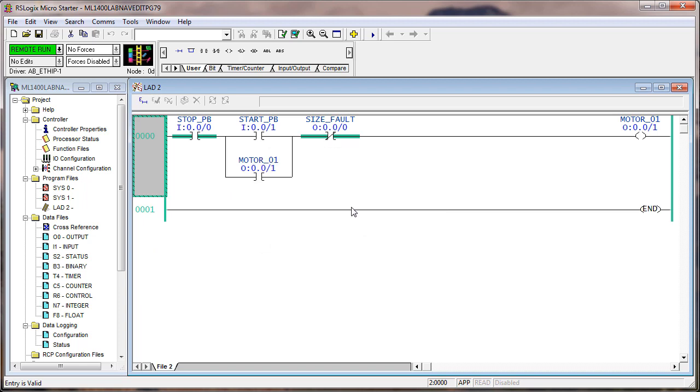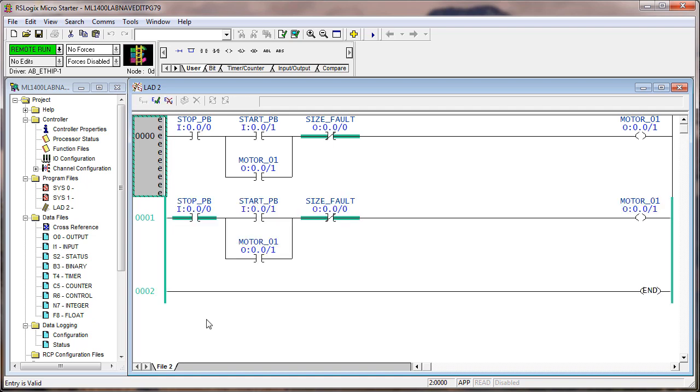And I'm going to add a second rung, and because they look similar, this one's the focus, so Control C, Control V, and I've got another one that looks just like it. And I'll move this one down here. That way the one I'm editing is down here. And I'm not editing this rung. You don't see any edit zones in front of here, right? There's no R's here. I'm not editing this rung. I made a copy of it. I did a Control C and then a Control V.